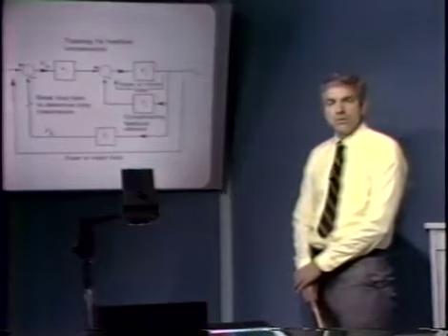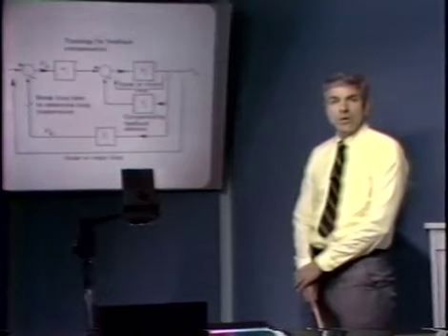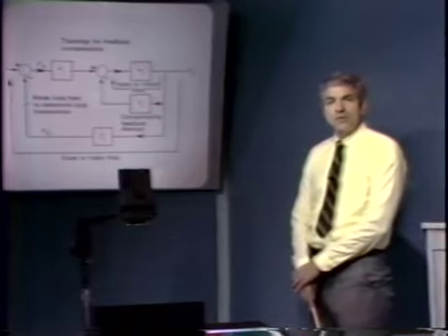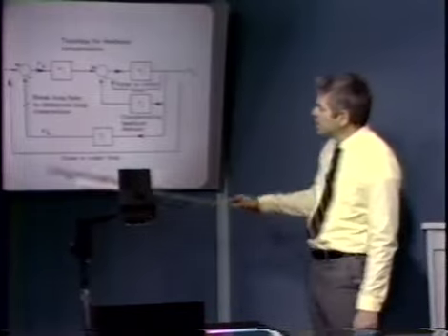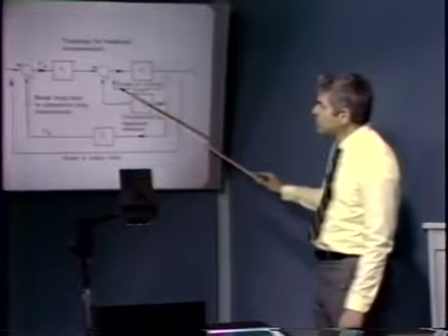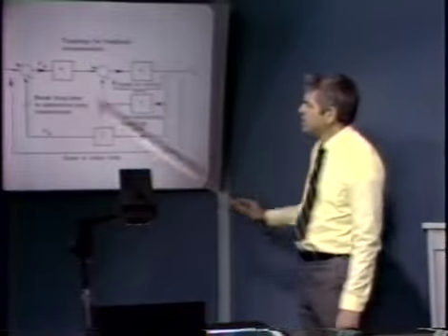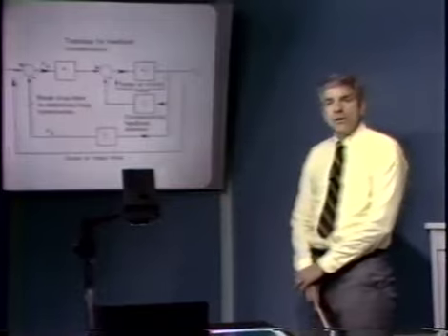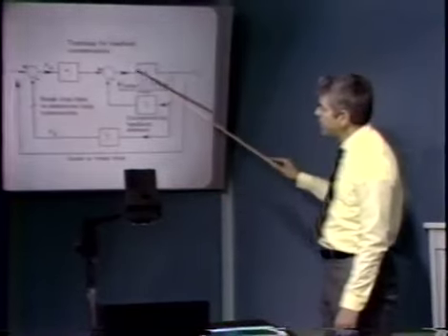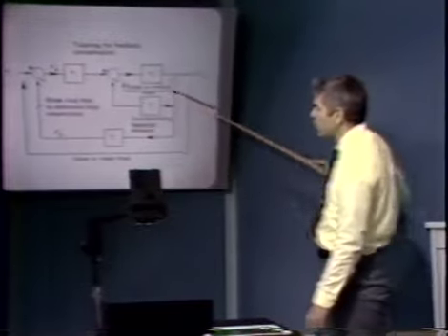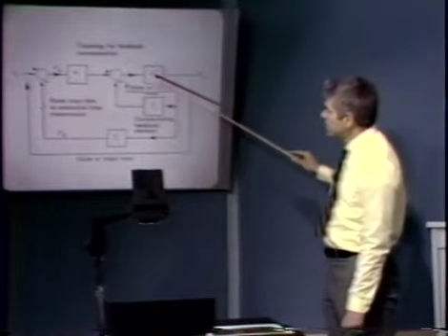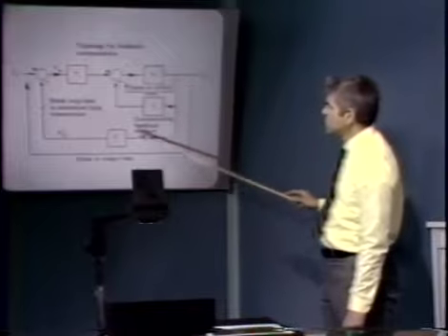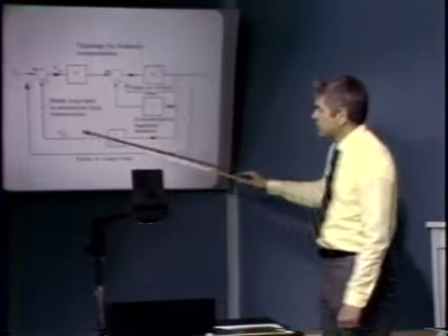We get more and more poles associated with the energy storage. It becomes more difficult to stabilize the resultant loop. Consequently, loops that contain fewer elements generally can be stabilized to have higher crossover frequencies than loops which include more elements. Here, the minor loop or the inner loop is a small fraction of the overall system, and so there's at least some hope that we're able to make this loop have a much higher crossover frequency than the overall loop. Consequently, we would find that the loop transmission magnitude of this loop would be large at the crossover frequency of the major loop.